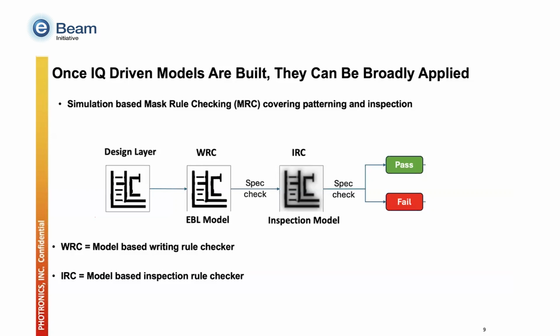There's a lot of different names for it, particularly when you get into very complex geometries, masks that start to push against the edges of the mask making processes or tools. This kind of MRC checking gets very, very important. The problem with MRC is generally it's all geometrical based. You have a rule, a table of numbers, minimum spaces, and how far apart corners are, contours, and how curvatures are changing. And you try to check the design relative to those geometrical parameters. But when the layout gets complicated enough, it's extremely difficult to do.